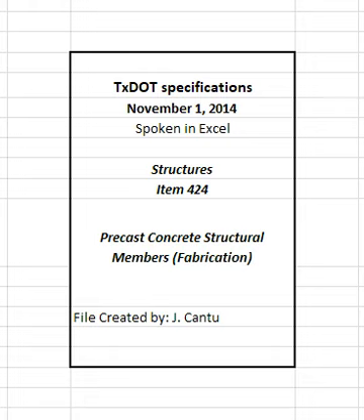4.2.2.2.1 Strand splicing. Do not splice draped strands. One splice per straight strand will be permitted subject to the following. Locate splices outside the members. Splice strands with the lay or twist in the same direction to avoid unraveling.